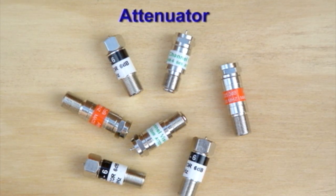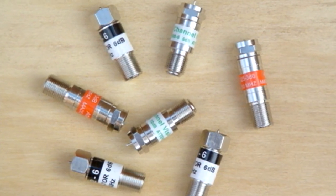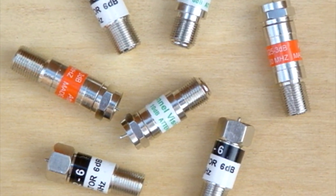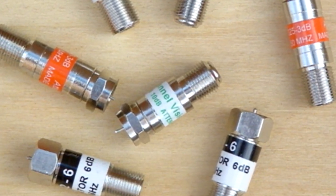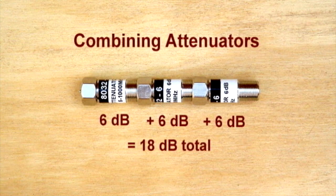The opposite of an amplifier is an attenuator, used to lower the amplitude of a signal. They typically come packaged in a barrel shape marked with the dB attenuation level. You'll find these commonly in 3, 6, and 10 dB versions. You can screw them together to achieve any amount of attenuation you need.